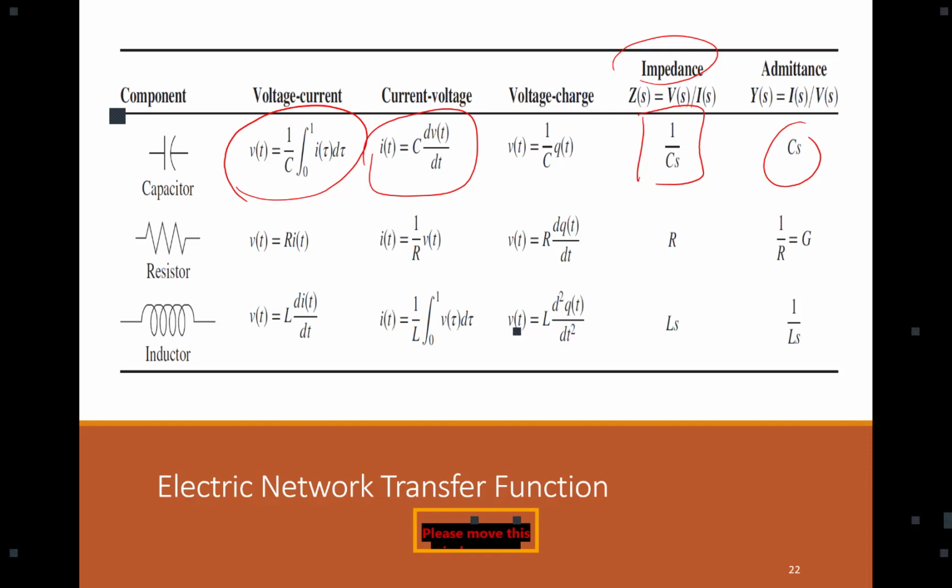Now you know that in circuit analysis it is j omega L, and for capacitance it is 1 over j omega C. Okay, and we talked about that. This is because we consider s equal to j omega when we have a sinusoidal input, which is just alternation without any damping, a constant alternation. So we don't have a DC or damping. Very good. Is that clear?